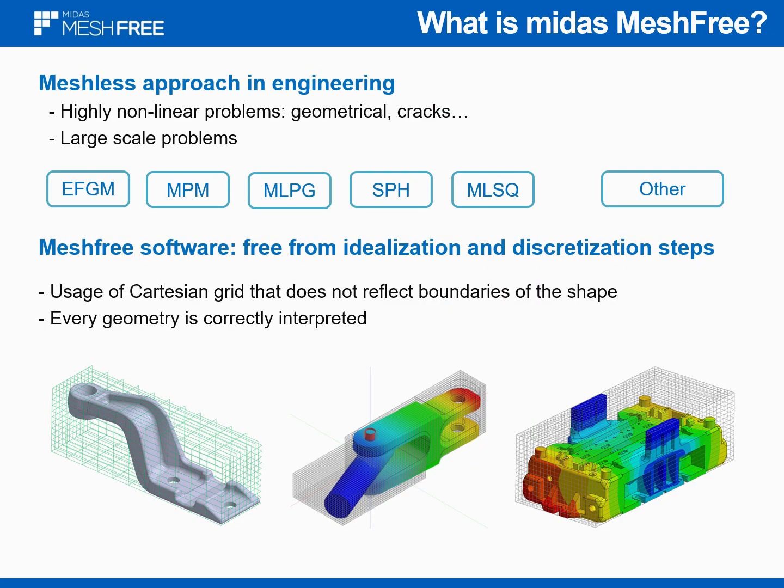The MeshFree concept in MIDAS MeshFree emphasizes ease of use and is directly oriented at product designers. This means MeshFree should free you from the laborious process of mesh generation and related cleanup. MeshFree uses a Cartesian non-conforming mesh, which does not represent the boundaries of the complex geometry, and because of that, every geometry can be correctly imported and interpreted.